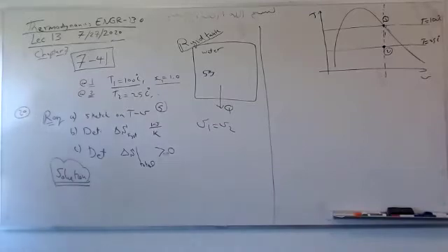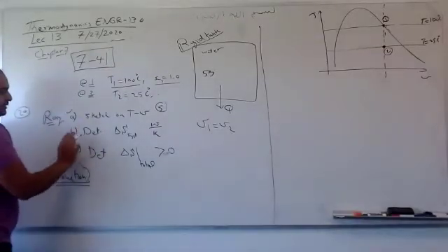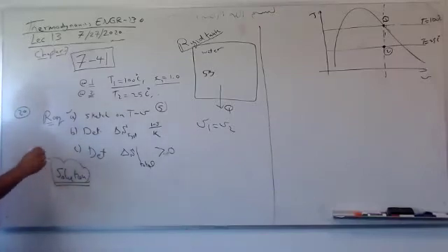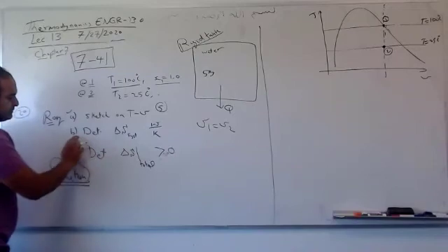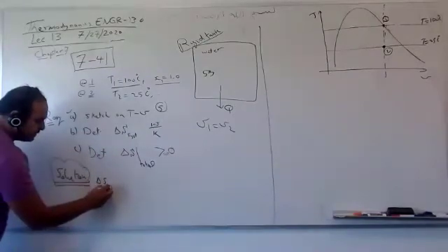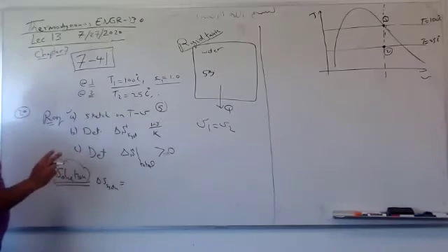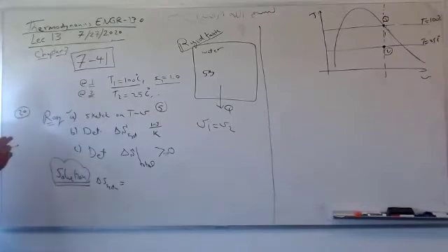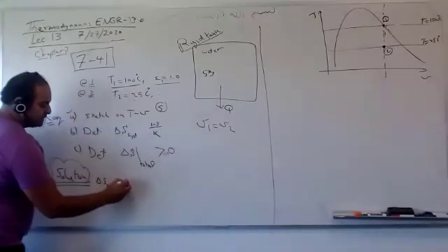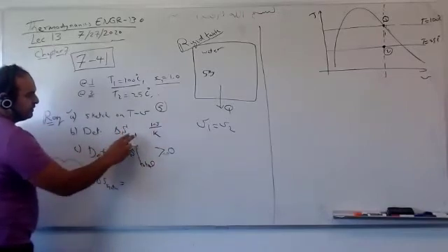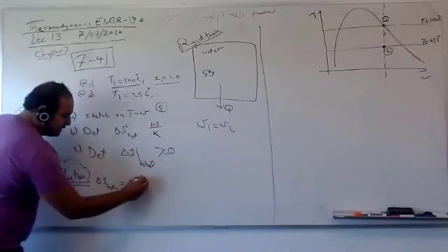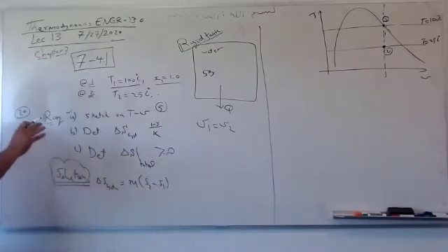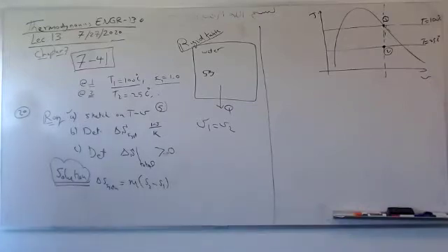Yeah. Okay, before you do anything, let's write down what you want. This is done. I used to write notes on the side to see what I want. I want delta S system, delta S total. So delta S system equal, this is heat addition to a system, correct? Which means this is steam table. So if you want specific or you want total, it's mass times S2 minus S1. Why? Because this is called steam table. I want to have S2 from state 2 and S1 from state 1.